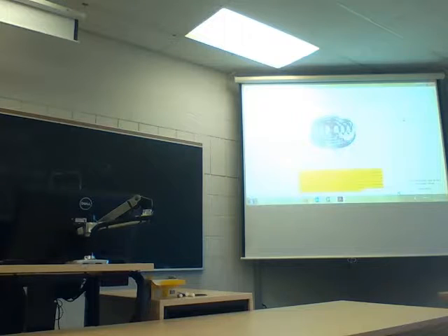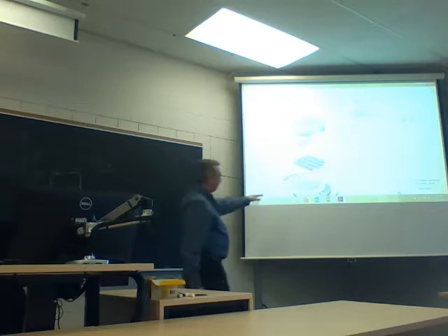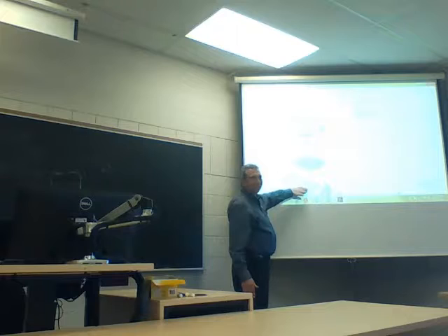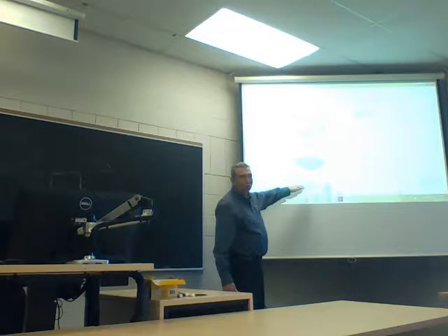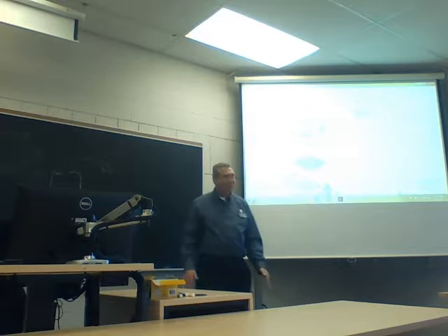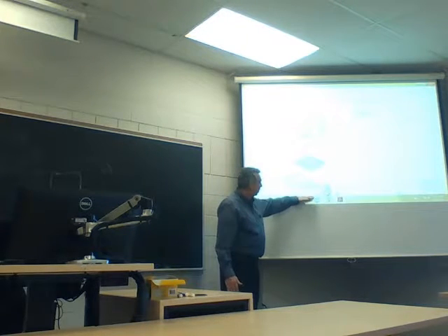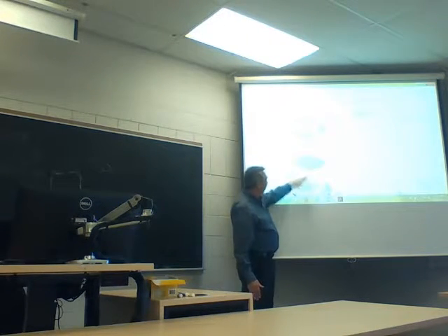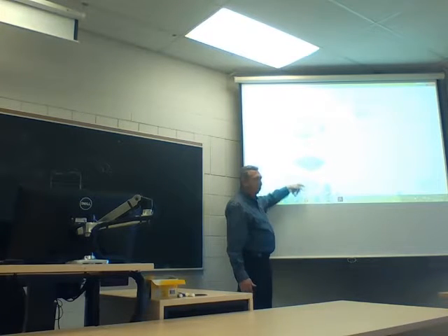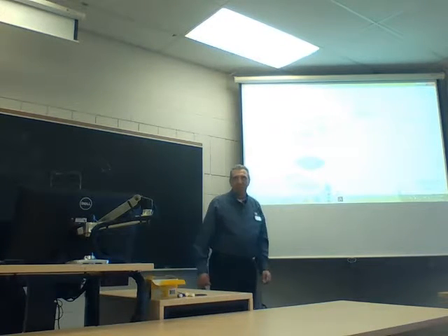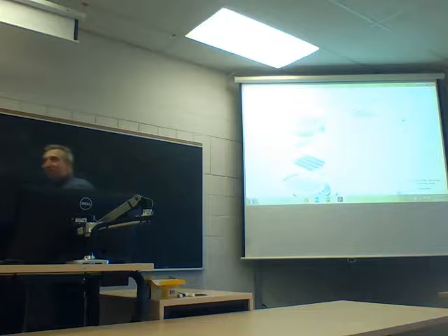So that's the plate type, the channel type. There you go. Do you see why they call it a channel type? Instead of having a plate over top of the holes, they actually have channels over top of the holes with more like a leaf spring that holds them instead of a coil spring, but they operate on the exact same principle. When the pressure under here is high enough, it'll overcome the tension and lift that up, and blows this and pushes the compressed air out.